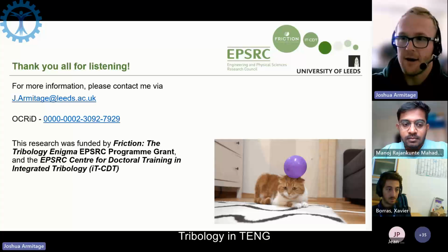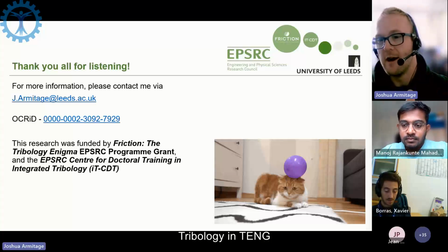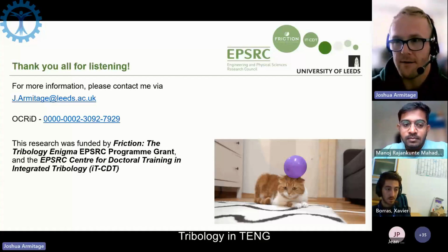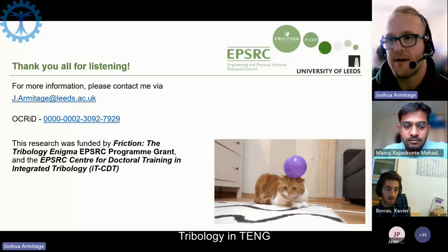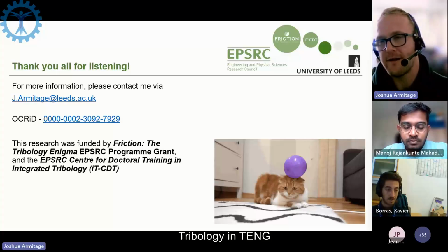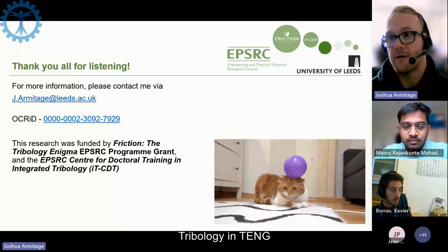We have interferometry texture scans of the two surfaces. We model them both being brought into contact, and essentially from that we get an idea of what the real area of contact is between those. The real area of contact, as well as the contact pressure and the distribution of that pressure, is between those two surfaces.